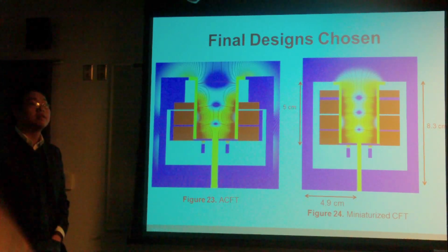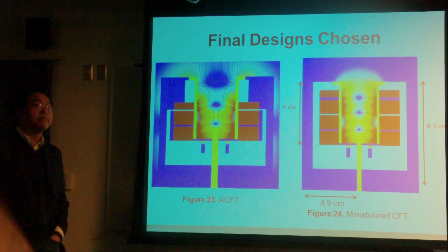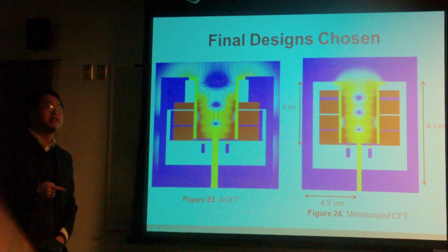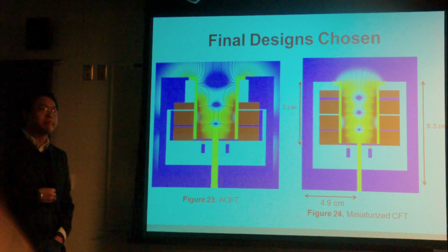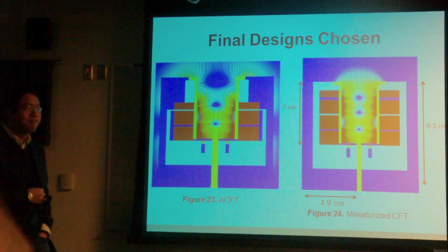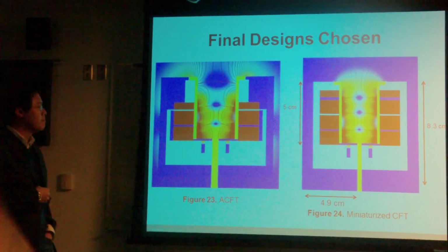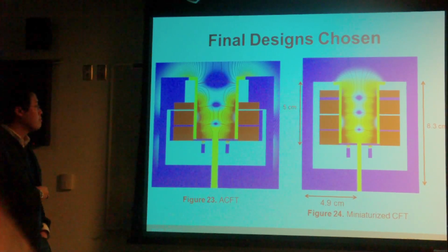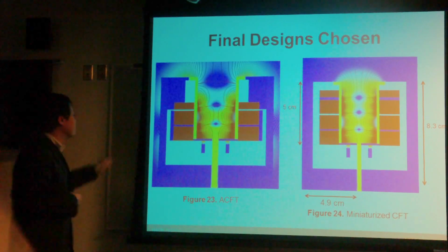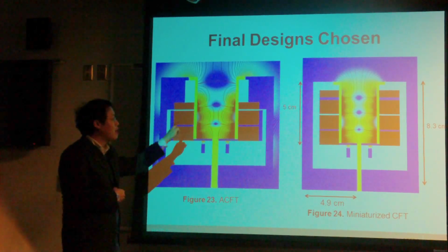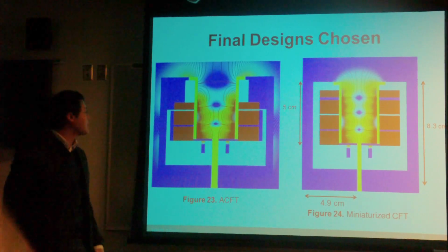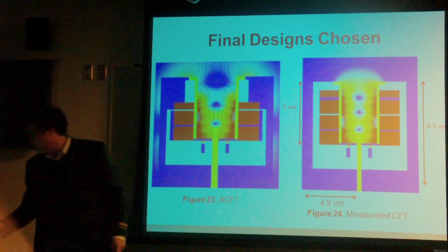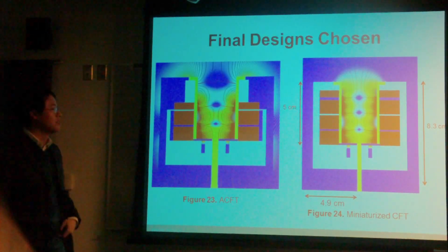Did you do anything to check if that would actually saturate? I did some saturation work after I talked to you about that, and it doesn't. Do you have margin to make it thicker if it saturates? Yeah, we could make it thicker. Which one? The spacer material we have here, the iron that we have, the 1018 steel. That's the blue, right? The teal color here. Well, here will be teal, but here it's more blue than teal.